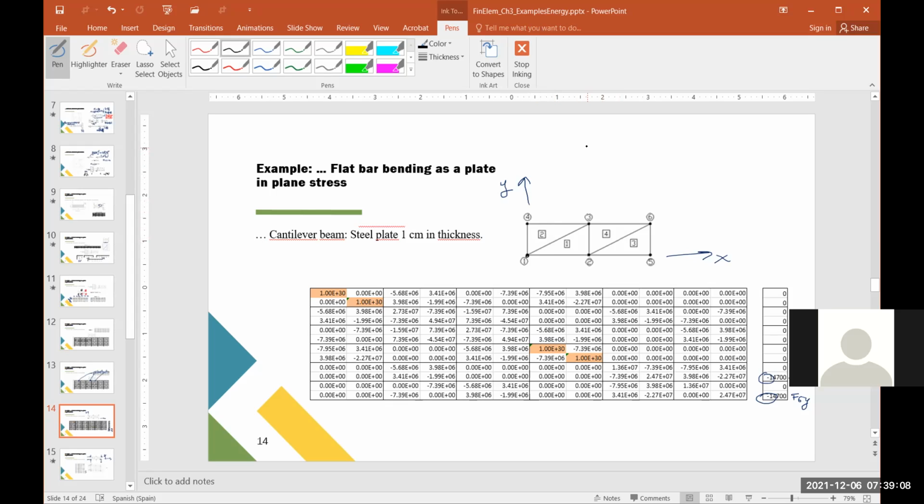You could have a different partition. I'm going to talk about convergence. For example, this is your domain, right? There are two important things here. First, this is clamped, and here I have a force. So these are the two most important characteristics. What we could try to do is represent adequately this side and adequately this, because here we are going to have the application of the force. These are the two main characteristics that we have to have in mind.